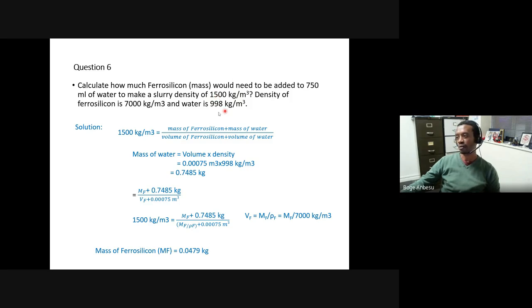So instead of using water as a medium for gravity separation, you can use this kind of medium. We use something like this in dense media separation. Obviously, the media here is denser than water. I'll talk about dense media next week, so no stress about that just yet.